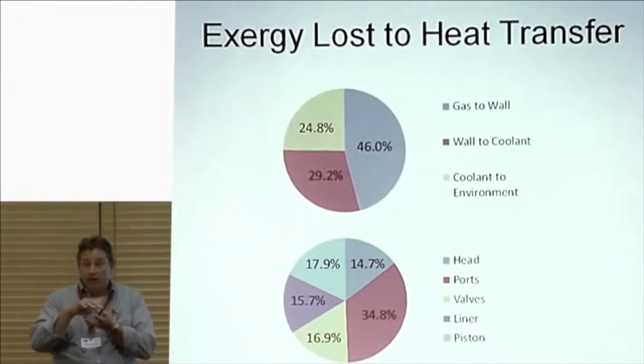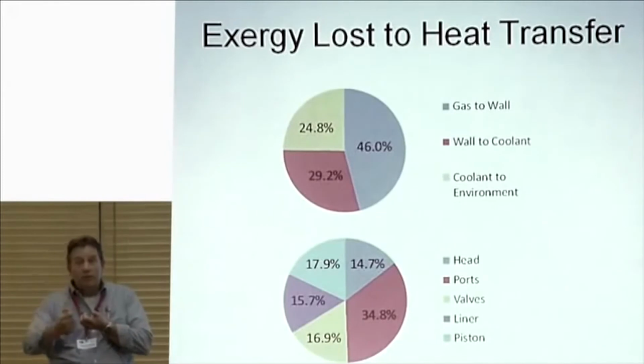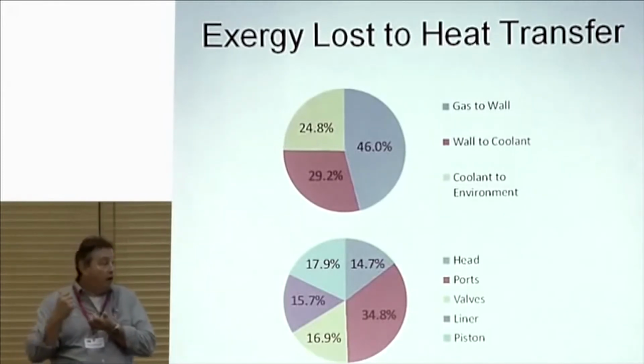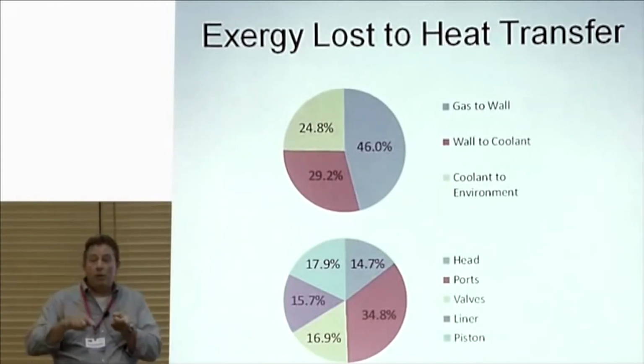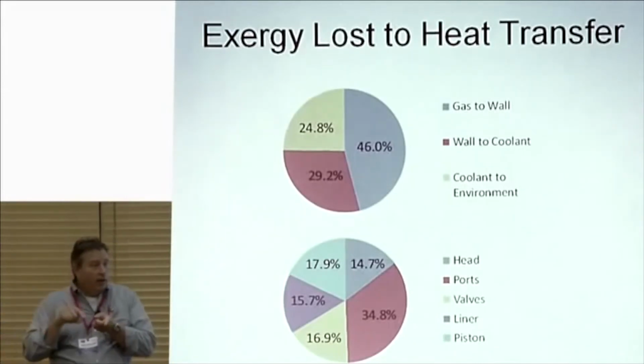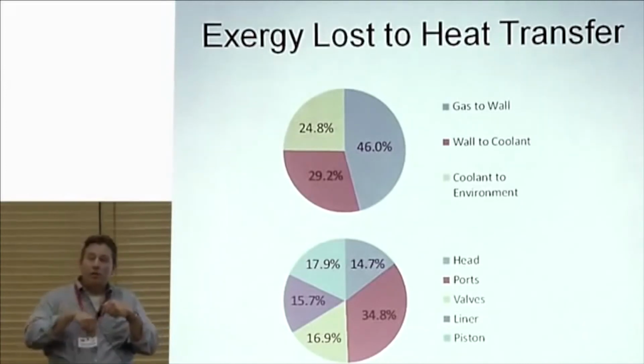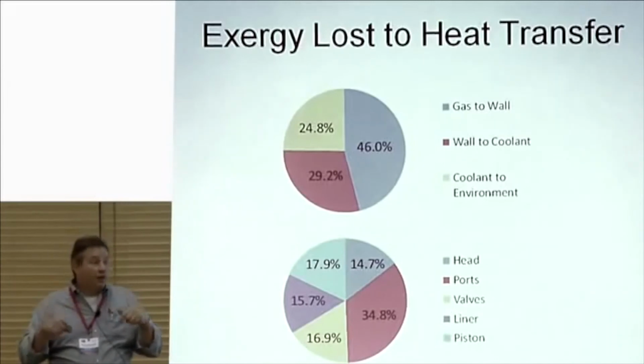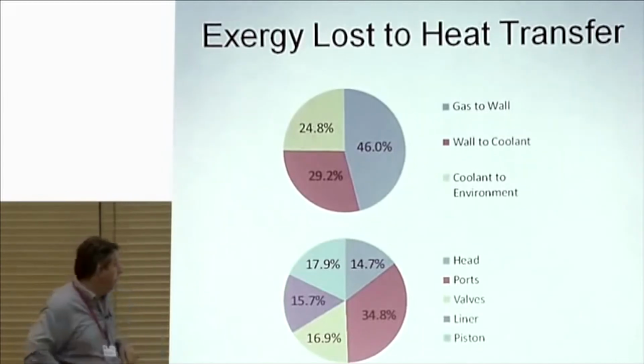The place where the velocities are really high, going through the valves, going through the ports. And you care about the port heat transfer. You care about it because you want to preserve the exergy to go to that first piece of turbomachinery. And you care about it because coming in, you don't want to heat up the fluid because it kills your volumetric efficiency. So you care about both ports. Those both should have thermal barrier coatings on them.